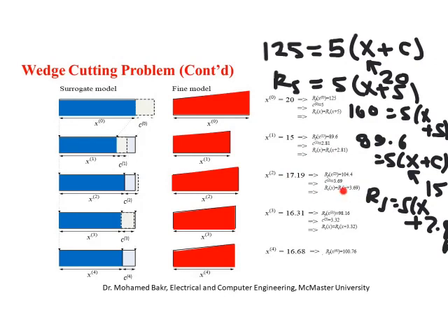I optimize that surrogate model again. So I'm gonna write it here somewhere: it's 5x plus, we agreed this one is 3.69 here. I'm gonna say this is a surrogate model, and this should be equal to 100. I solve now for the new x, and you divide by 5 and so on. You get x equal to 16.31. This is now our new design.